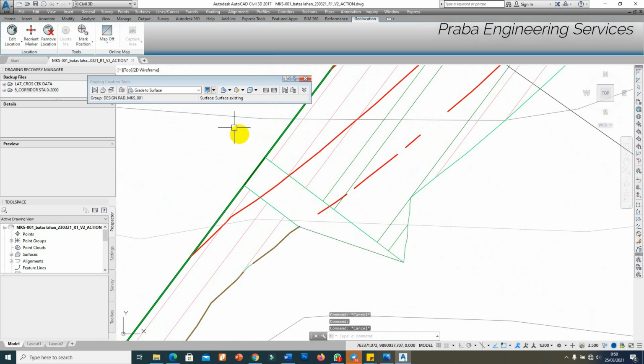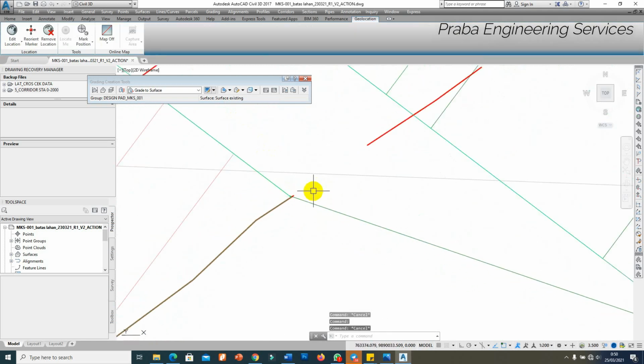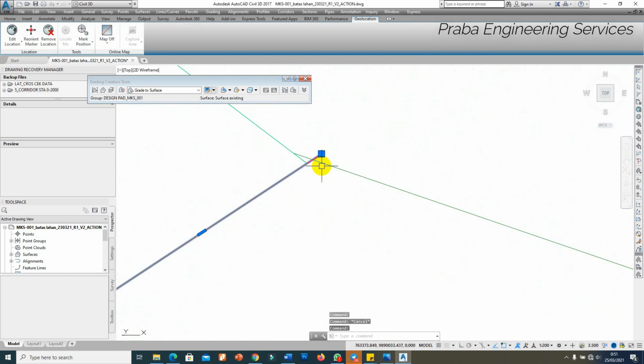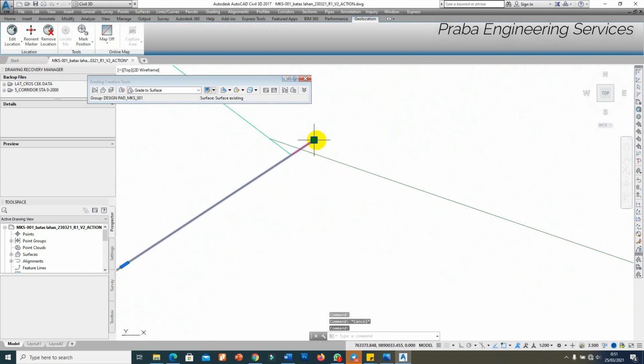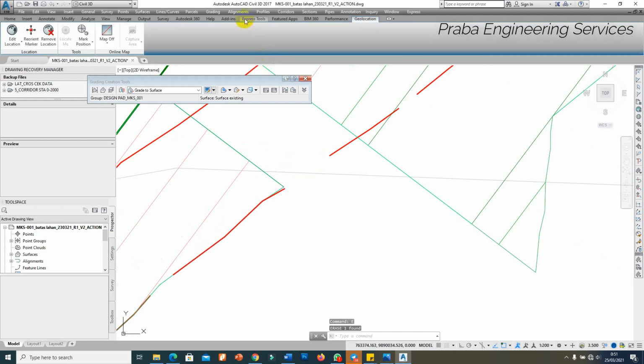If we want to create infill, but there is something happening, which means there is no connection from here to here. Sometimes when we make it on for the objects, we have the guidance line. The guidance line sometimes makes mistakes. So I want to delete this one and repeat again, draw feature line. Make sure the connection on the end, this one and to this one. Okay.